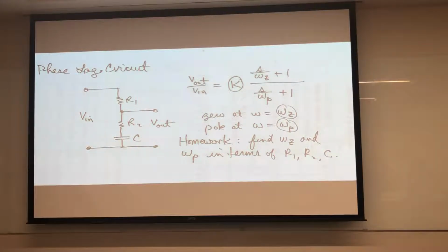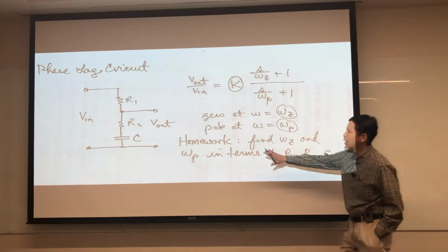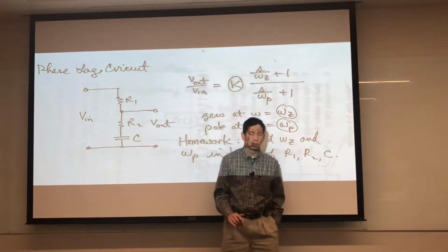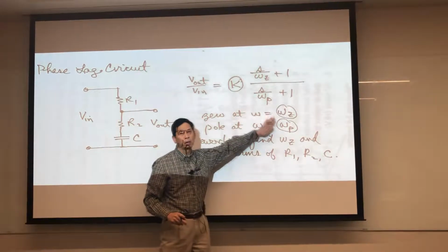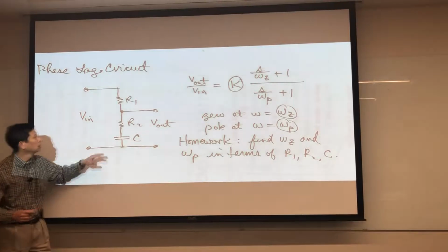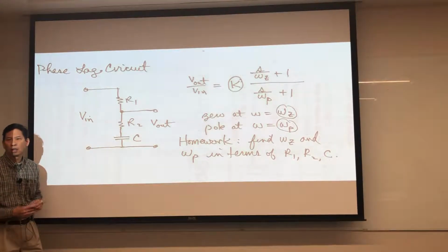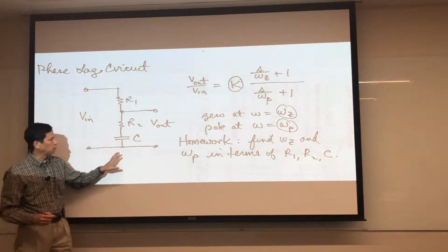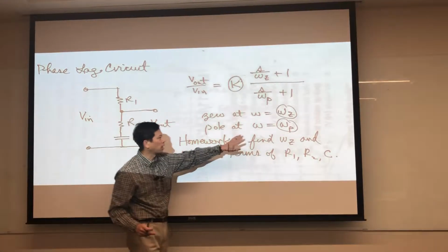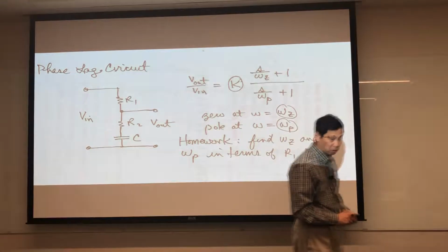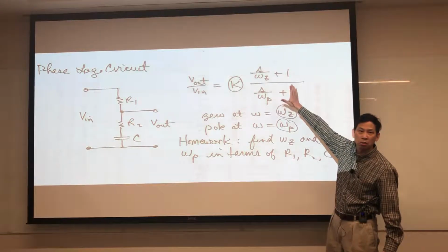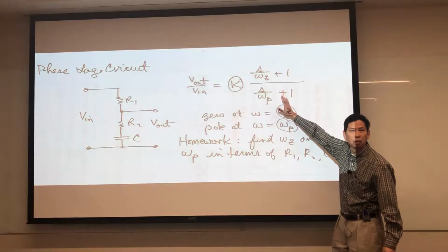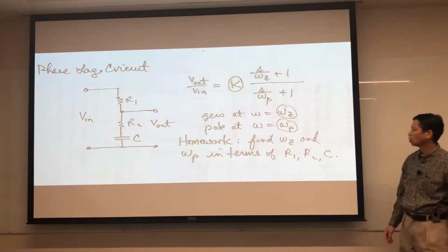Okay. So several decades ago, if a person said, I wanted to compensate my system with a phase lag, he might come up with a network like this. We call this a network of devices. And he said, I know that I have a certain omega Z and omega P and a K that I would like. I need to find R1, R2, and C. So this is a network, and this is called synthesis. Network synthesis is basically coming up with a network that produces the desired transfer function. Today, we generally don't do R's and C's, except in specialized applications. We will take that transfer function, and then we discretize it, and then we write difference equations, which we've done for exam 1 and 2. All right, we do it with a computer.